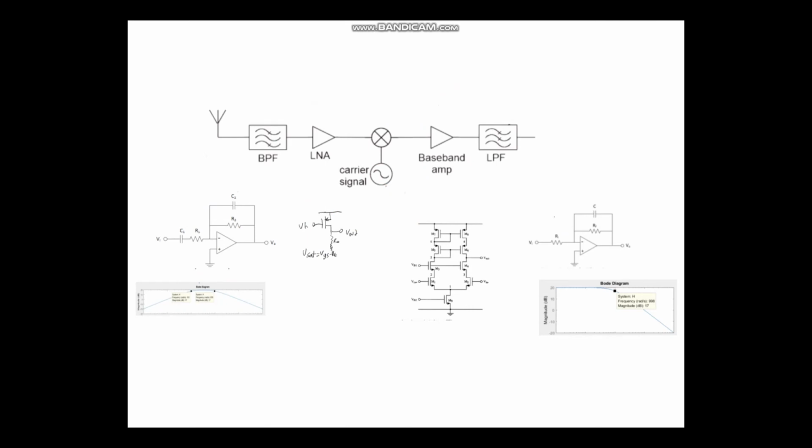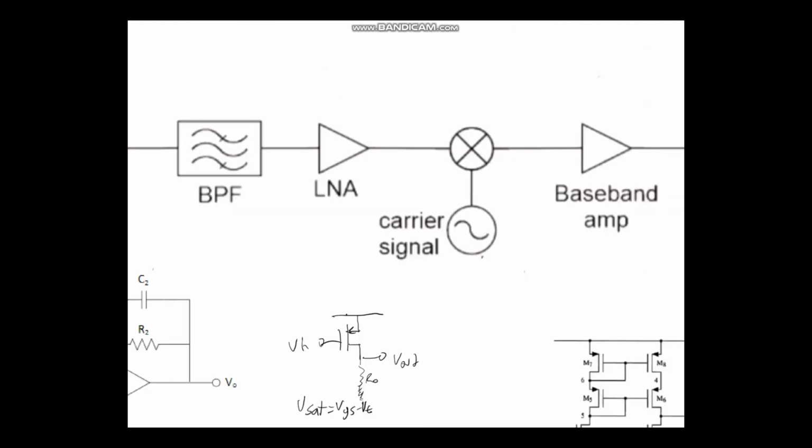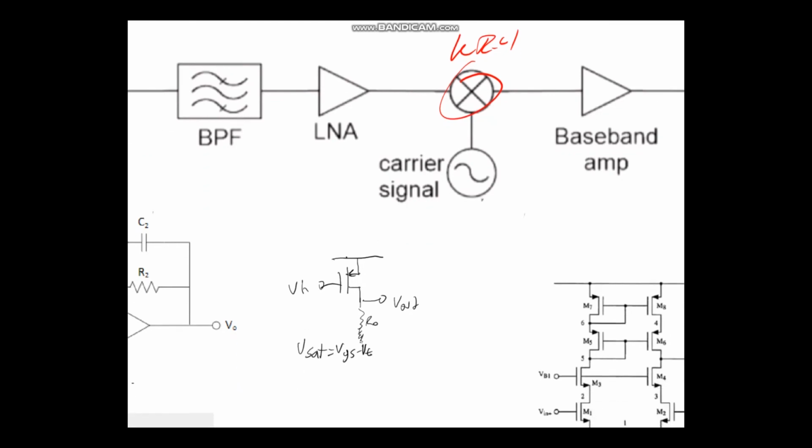Having previously discussed the signal flow from the input to output of this whole system with the receiving end of the cell phone, we can now talk about just a basic design that we talked about in our pre-work. And if we can set up the parameters just so of a filter to make it pass only the frequency that we want. The low-noise amplifier is going to set up the signal, give it more gain to go into the mixing. The mixer, we talked about the mixer in KI4, but we can talk about the low-noise amplifier in a small way here.